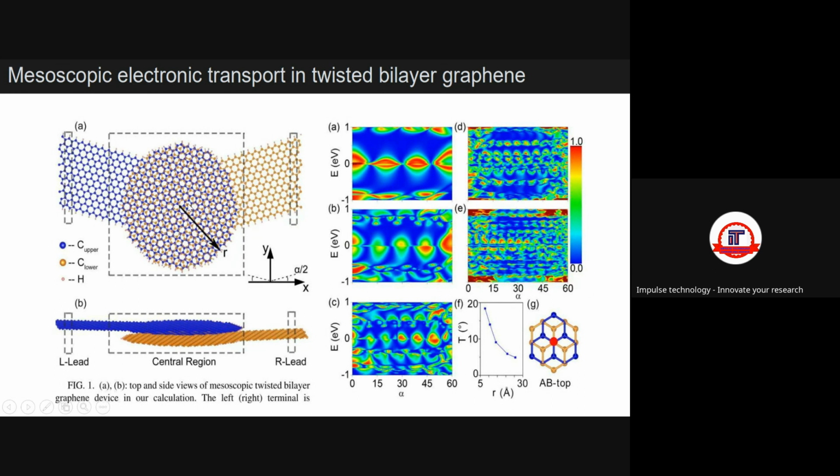Here you can see this is the twisted graphene sheet. We have the circular region, left region, and right region. We have an angle position where you can select which left and right positions you want. Accordingly, you can find the E-k diagram, transmission coefficient, and other properties from different variations. You can also find the eigenstate, potential distribution, and many more properties by rotating and twisting the sheet.